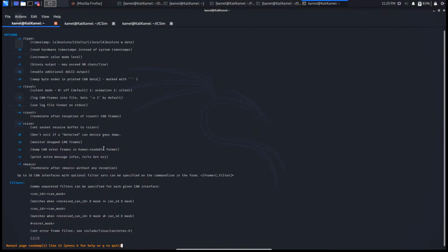So this means the CAN bus can get very noisy. You have a lot of data that's flying back and forth, and you're not interested in most of it. You're just interested in 1 or 2 arbitration IDs. Well, obviously, you have to have a way to filter this huge torrent of CAN bus data into something that you're actually looking for. You can narrow down the CAN messages that you're hoping to reverse engineer, that you're hoping to identify, that you're hoping to observe and understand their operation.